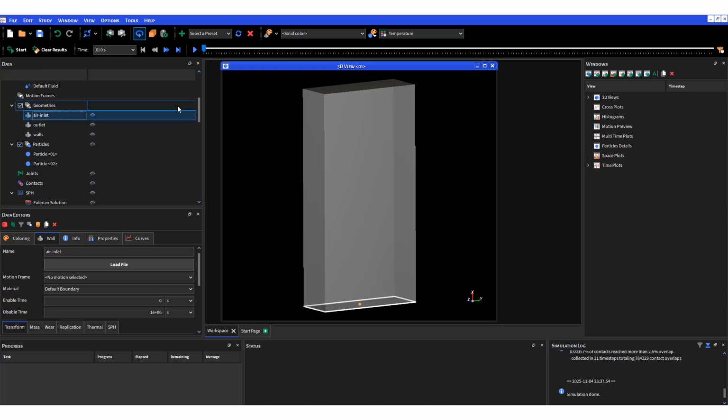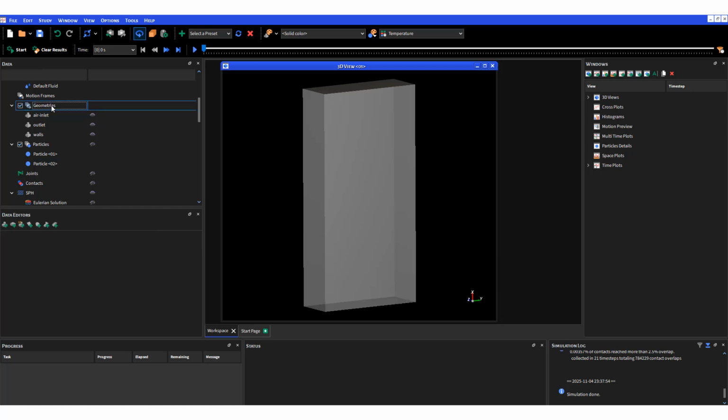Here I do not have any surfaces, so a surface would allow me to add particles or extract particles as an outlet. But here I'm treating everything as a wall for the particles, and the way I'm adding particles is with a volumetric injection or inlet at time 0.